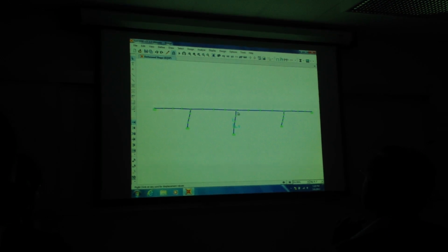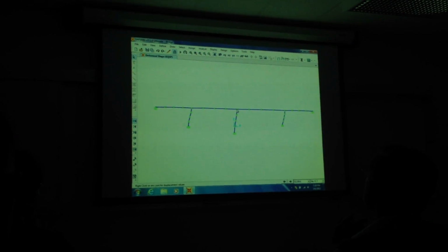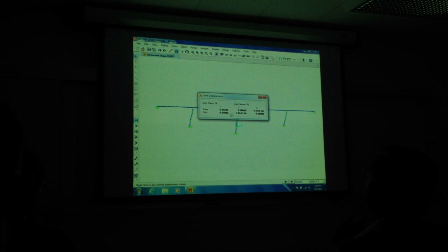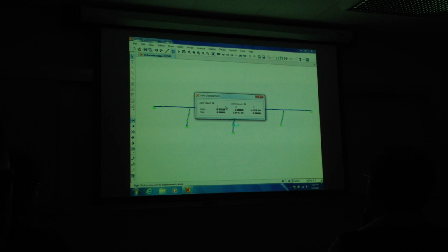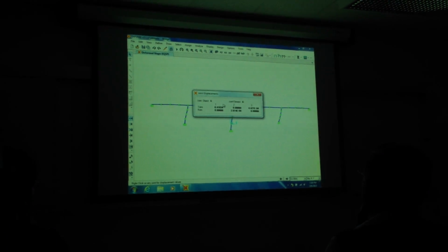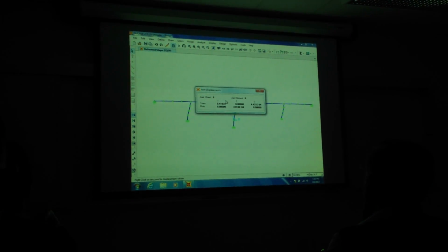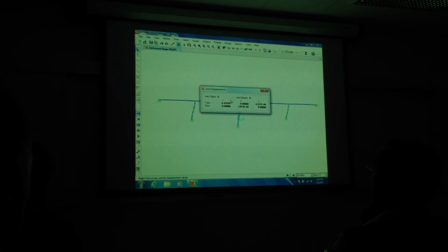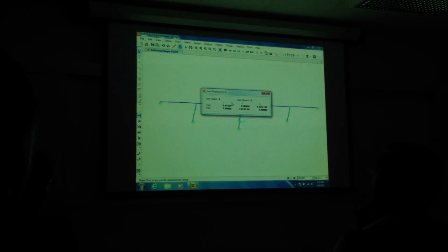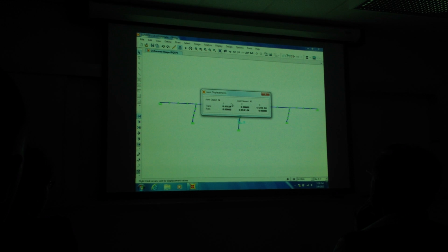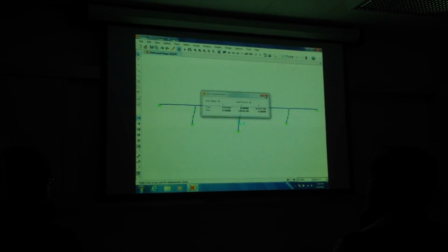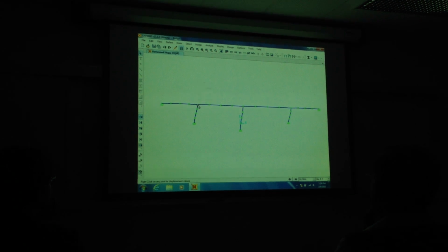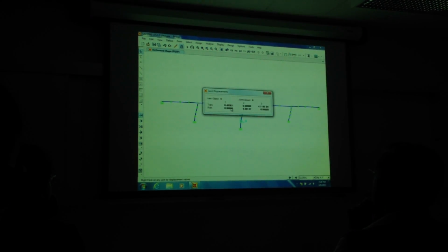Actually very stiff, so the displacements would be the same. We can look at that. Let's right click here. So look, 0.41 feet. So we're getting the same displacements that we got from the time history analysis for the same earthquake, because this is linear elastic. The spectral plot is representative of the maximum displacements, right? That's what it's giving you. So it's approximately the same value. If I go over here, and right click, 0.41 round it off.